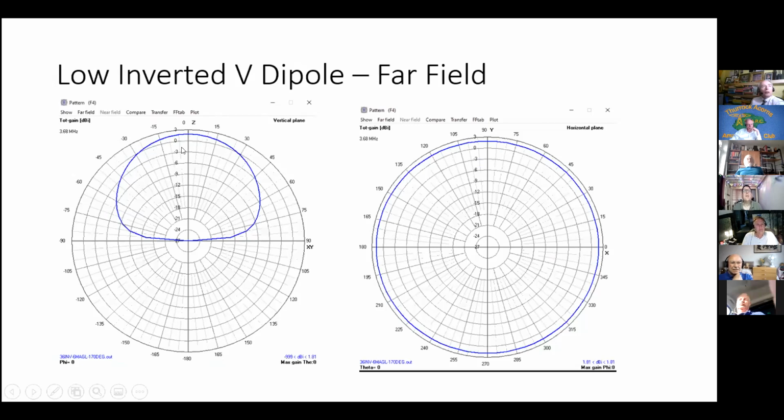And if you go round to say 15 degrees off the ground, follow that circle round, it's about -8 dB relative to a dipole. It's rubbish, basically, for DX or for local ground wave stations, because it has very little radiation parallel to the ground.